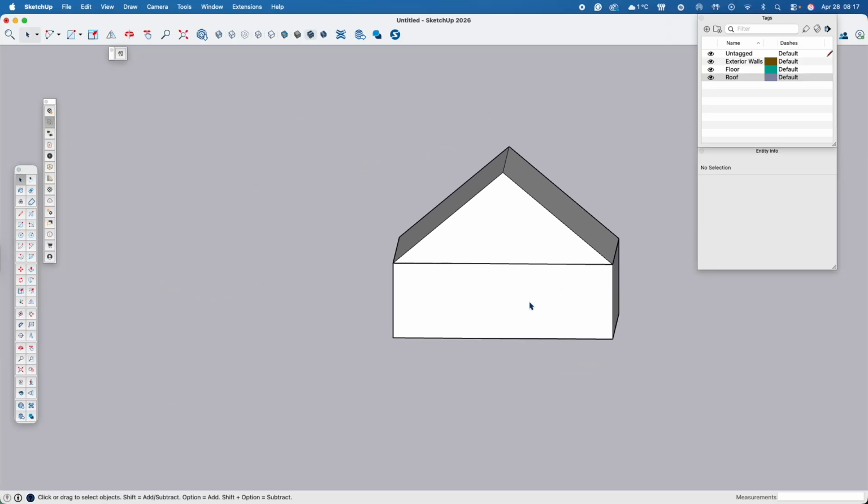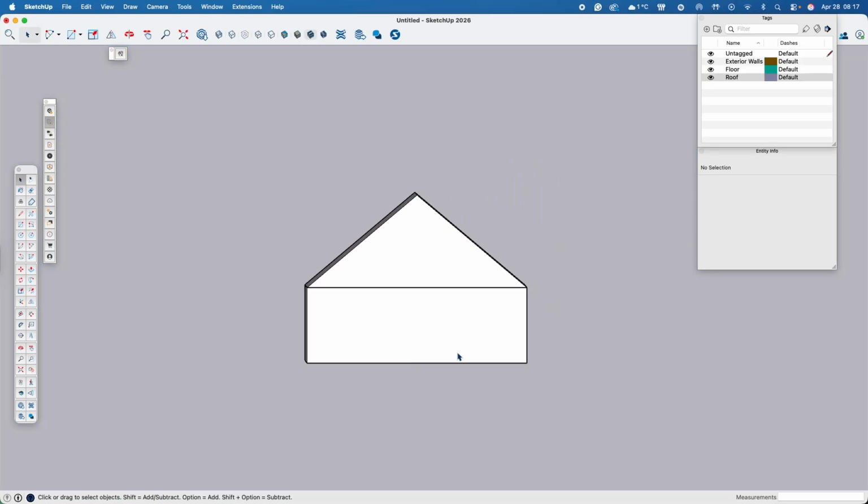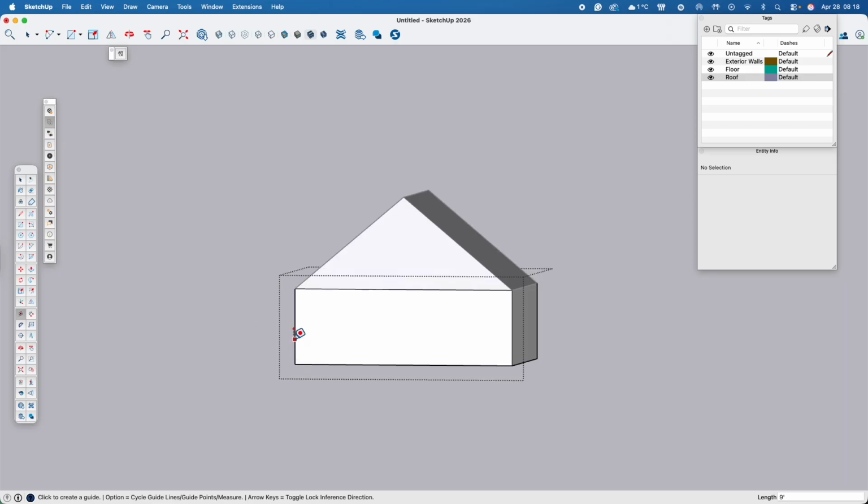Now you have it. Okay, so now in my house, I want a door and 2 windows. I want my door to be in the middle of the wall, like literally in the middle of it. So I will enter my group, the walls group. I will take my tape measure, T on my keyboard. I'll put my starting point of the tape measure along one of the walls, click once, and then, as I did for the roof, I will go along that line until I get my blue dot. My blue dot says I'm in the middle of my wall.